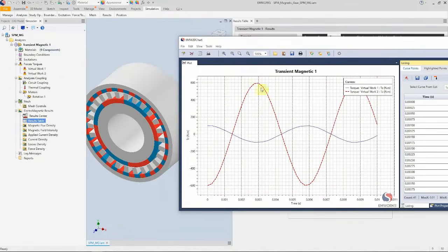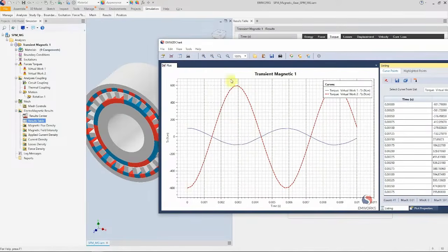Each of these points can be an operation point. For example, if we choose a phase shift between inner rotor and outer rotor, we will not get any torque like this point. Both torques will be zero. But with a difference between these two rotors, we can extract the maximum torque of 600 Newton meter with the ratio of 1 to 6. So from this simulation, we found out the maximum available produced torque.